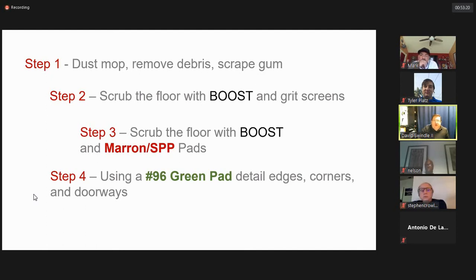The reason is they're not an ammoniated finish. Ammoniated finishes do something really unique. When you use an acrylic floor finish like we use on resilient flooring, that bit of ammonia allows each coat to stick to each other, because it softens the coat below it, so it sticks really nicely.